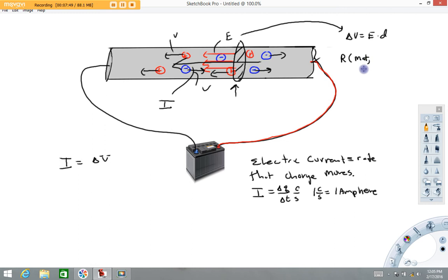Materials like metals would have very low electrical resistance. It's a function of the length of this object here. Typically, the longer the object, the lower the current. Therefore, the longer the object, the higher the resistance. And it's a function of the cross-sectional area, meaning if we're looking this way, the larger that cross-sectional area is, the easier it is to push current through it.